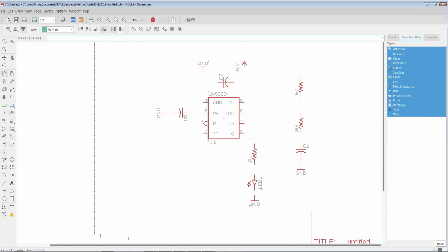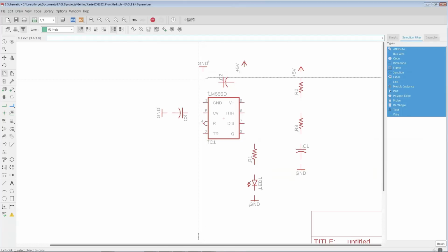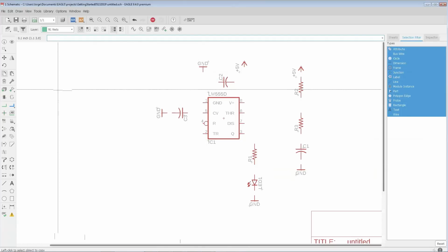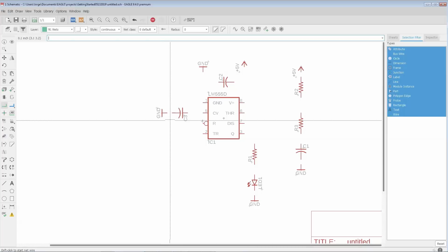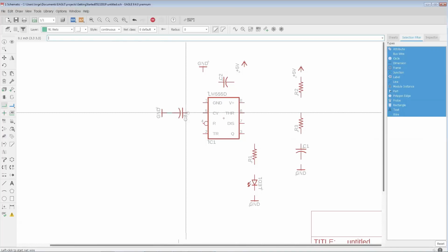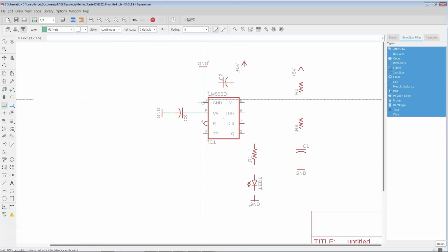Also, make sure that when you're placing components on the schematic, as well as defining connections, always work on the default grid. Please never change the grid. If you prefer the metric system, that's okay. Change the units to metric, but leave the sizing. Leave the default grid: 0.1 inch or 2.54 millimeters. Very, very important. Your life will become very difficult if you change the grid.